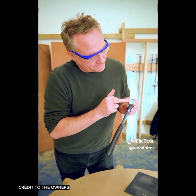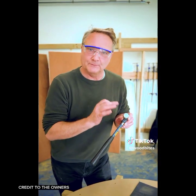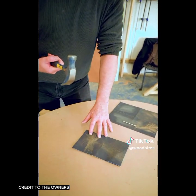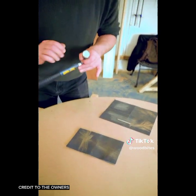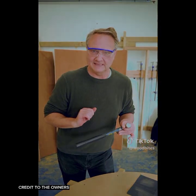Secondly, look at the hammer. The hammer should be smooth on the end. If it's not, this will cause problems and it will bounce all over the nail. So, a piece of sandpaper, preferably one that's used for metal, and you're going to rub across the face until you get the face of the hammer nice and smooth. And now we're ready to hammer.